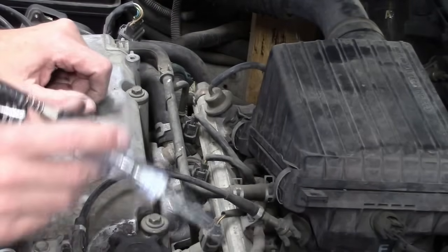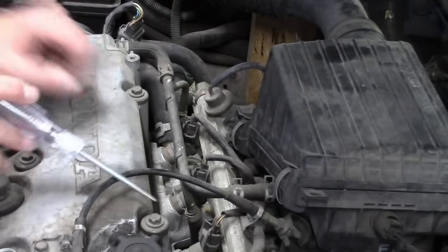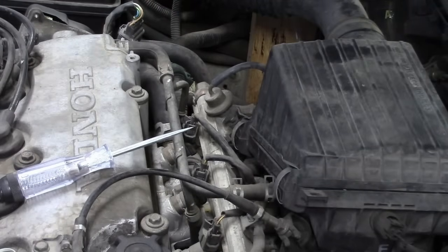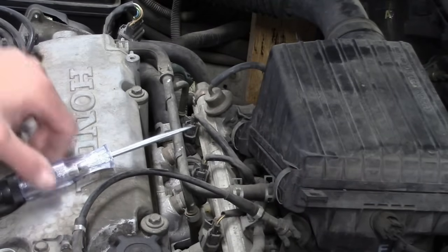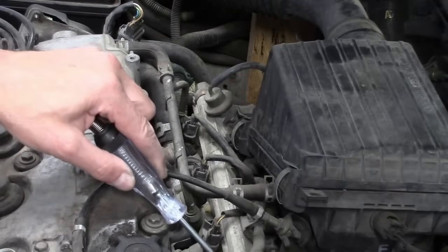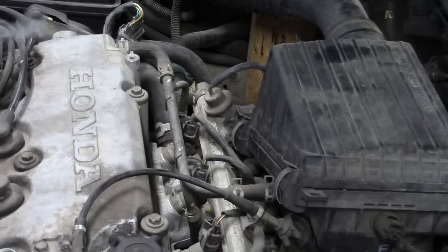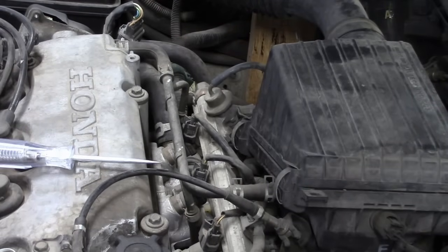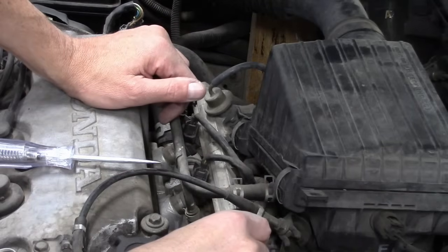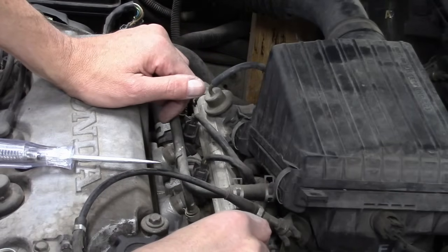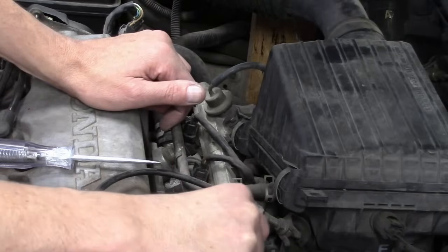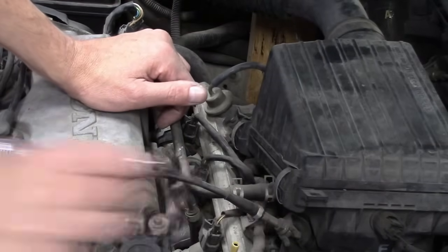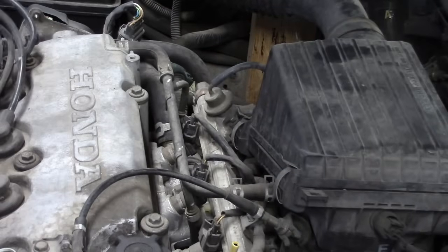I think it is the first method, but either way, I can easily test this with my test light and confirm if there's signal or not. And that's without even looking at a wiring diagram or anything. It is one of those 2 possibilities. The different colored wires are either individual grounds or individual powers. They're almost guaranteed individual grounds, and I can test whether those turn on and off. All I'm going to do is take a back probe and feed it into one of the different colored wires. And in one step, I'm going to be able to tell that I am correct, that this is going to be a ground side switch system.